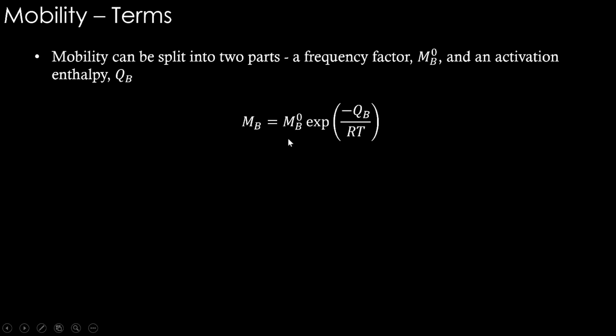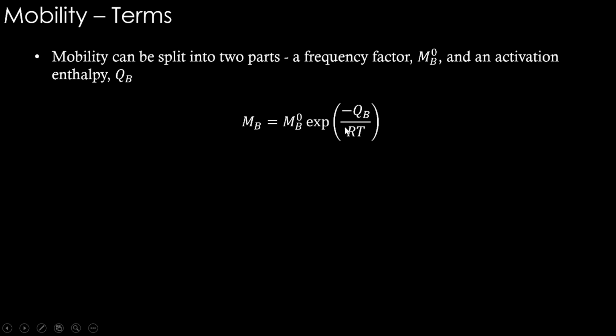You see, it looks largely similar to diffusivity, because if we talk about mobility, we say a mobility related term multiplied by the chemical potential gradient. This is what is going to decide the flux. But when we put the chemical potential gradient, it takes care of the driving aspect. But still the other aspects, the activation energy part, is going to remain in the mobility part. So it has to have the format of the diffusivity, where a frequency factor, a pre-exponential factor comes, and activation energy comes. So we need to model these things in order to use mobility in the databases. We will see about that shortly.